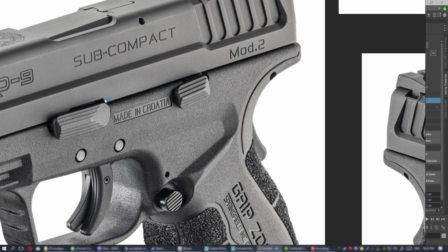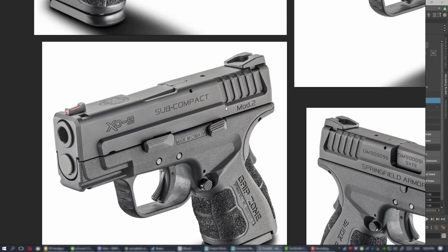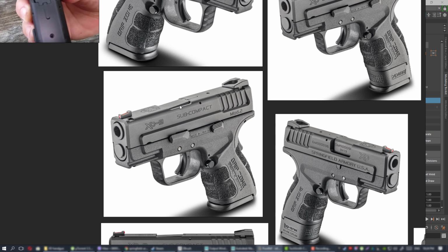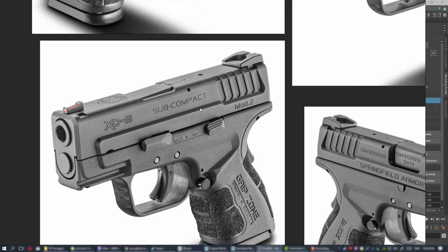You can see that this cutout is going to be traveling all the way right here, and when the magazine is empty, this lever comes up and fixes the slide in the open position so that you can load another magazine and pull this guy down and the slide goes back into battery.